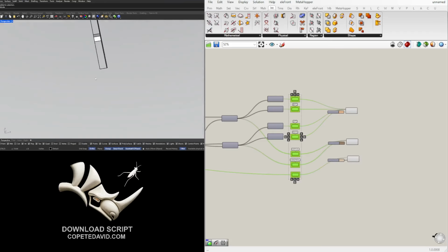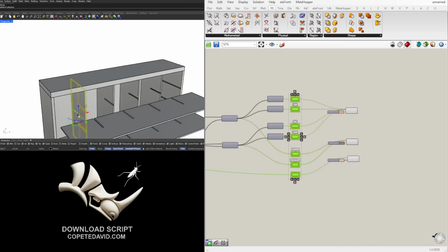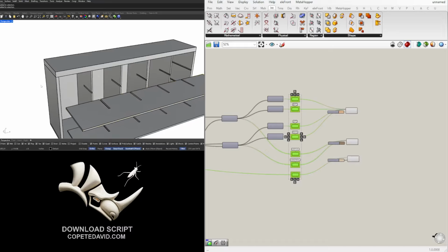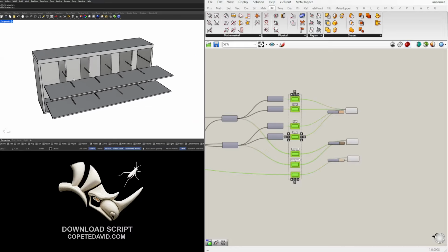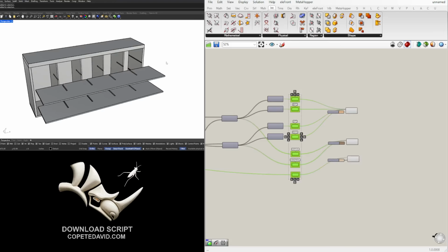But when you have a CNC router, you're going to have the radius of your bit be a limiting factor here. So you actually have to kind of create some fishbone geometry here. So this way, when you intersect this one and this one, it's not visible, but it also intersects perfectly. And from there, taking these horizontals and verticals and deconstructing it so you can CNC this.